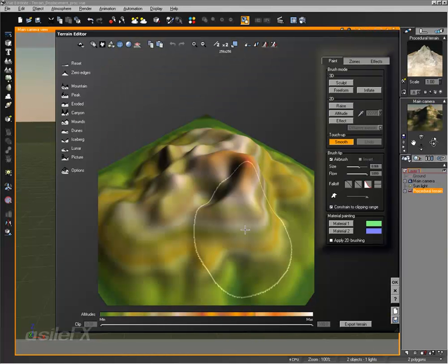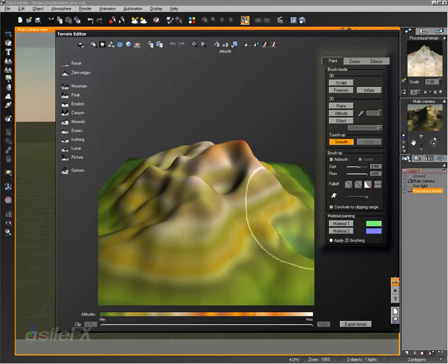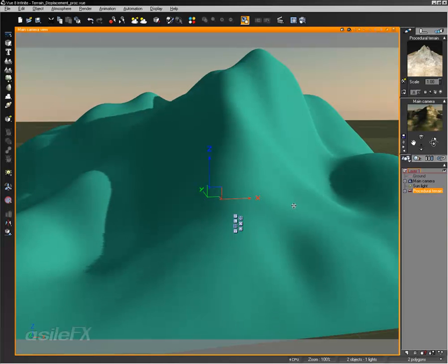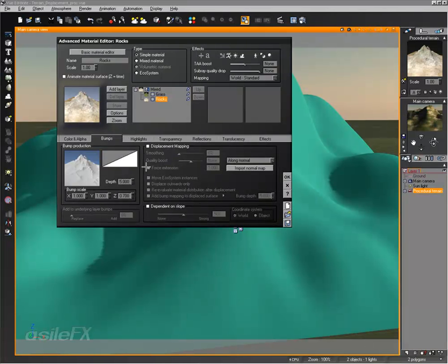This is actually the part of the training that I did put off for last for recording because of a lot of these issues. What I did find worked this time was I turned off the displacement mapping in the material, saved the scene, then purged the memory again, and then was able to convert the original terrain over to a procedural. So it's just a memory issue. Hopefully it's something that could get fixed. So now we can turn back on the displacement mapping,